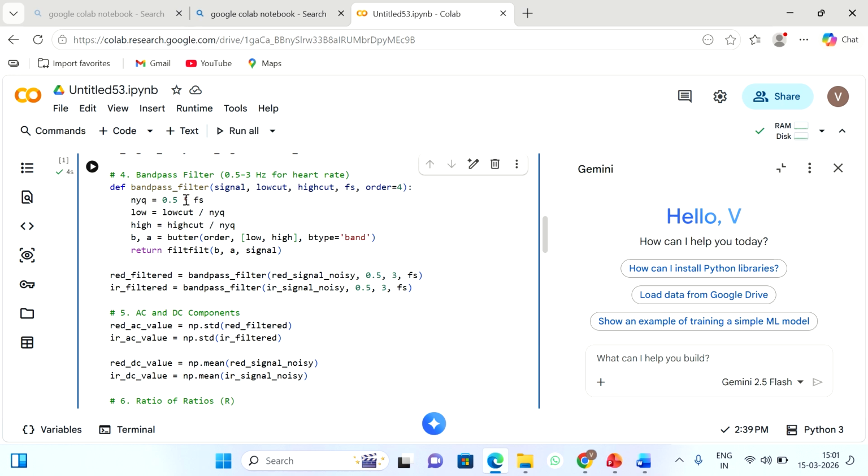Actually, the sampling frequency should be higher than or equal to that. That is why the aliasing problem occurs. This aliasing problem will be overcome by using anti-aliasing filters. So to avoid this, when starting the sampling of the signal, we have to consider the Nyquist criteria.